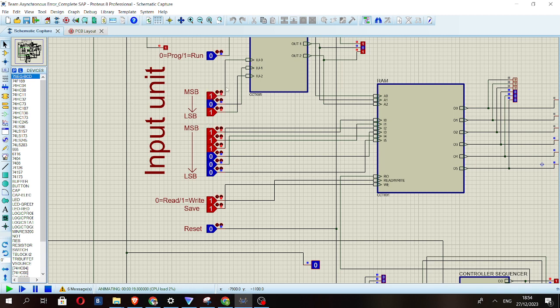Let us continue doing this. Now at 101, we will save the first number, that is 21. So we will save the binary of 21, which is 010101, saved. And at address 110, we will save the binary of 15, which is 001111, saved. Now we have saved the instructions to their corresponding addresses.